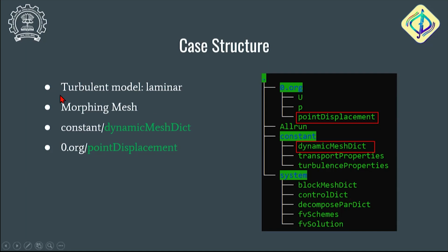So we can see that our mesh is moving, unlike the AMR case, where the mesh is split into many more meshes and gets refined into smaller cells. In the morphing mesh, the mesh will deform and distort as the boundary moves.